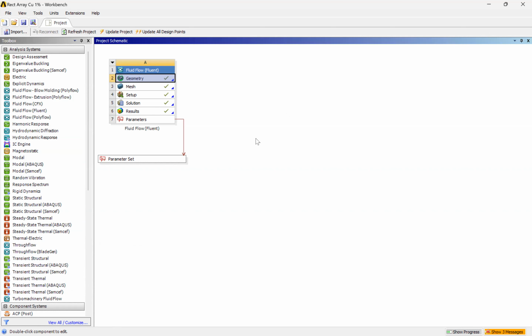And when you select it, these options will come. At first you have to create the geometry, and then there is the mesh that we have seen. Then you have to do the setup. That is the next step, what we are going to do maybe in this class or the next class. After creating the mesh, you have to incorporate your boundary conditions, and also you have to choose some solution algorithm, some solution models based on laminar flow or turbulent flow.